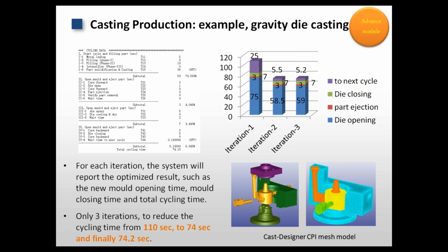And then you could use these optimized cooling channel parameters to find out how to control your cooling channels, the water velocities, and the cooling channels' HTC for the manufacturing.